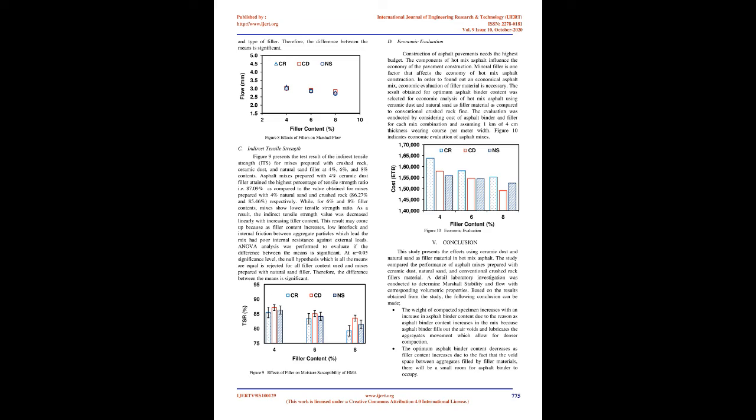Flow decreases with an increase in filler content, due to the fact that as filler content increases, friction between aggregate particles increases. The flow values at 4%, 6%, and 8% filler content of the mixes for all filler materials are within the limits of the Asphalt Institute MS-2, 1994.